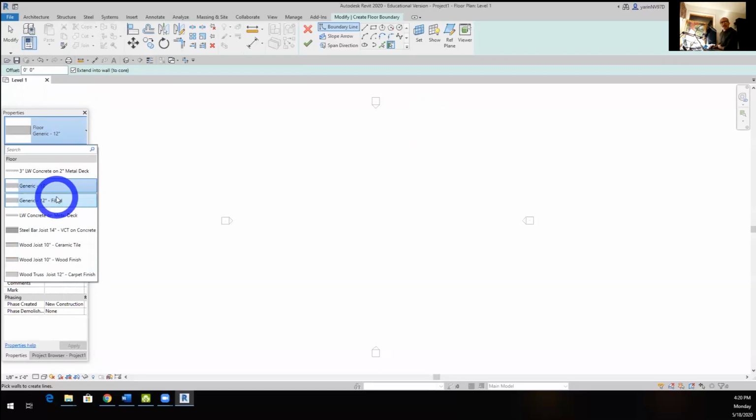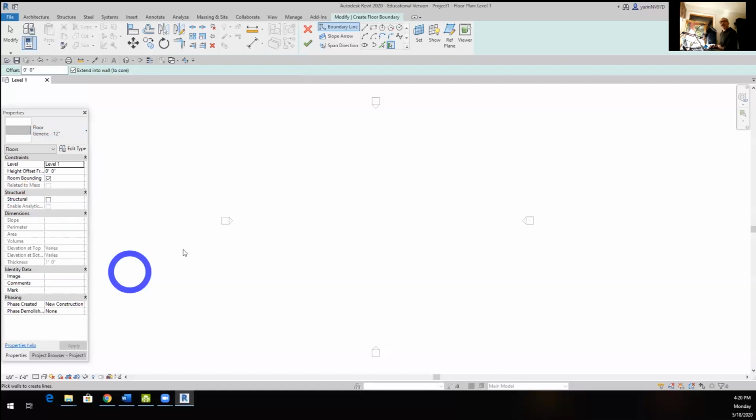3-inch lightweight, not on that. 12-inch generic, let's go with 12-inch generic. For now, click 12-inch generic, and now you have that selected. And I'm going to go ahead and use the line tool right here, and I click that. So I'm going to come in, and I'm going to make myself a floor.